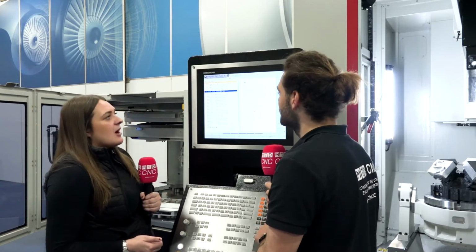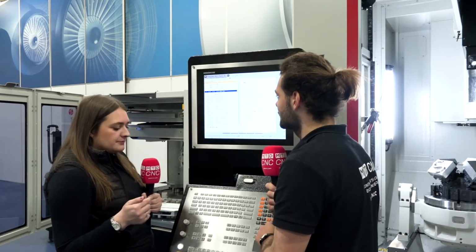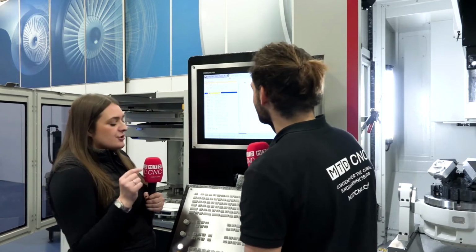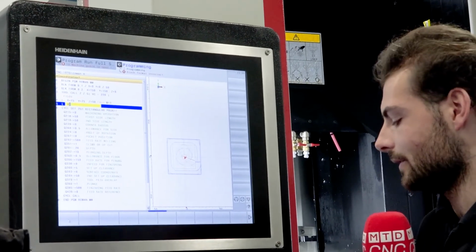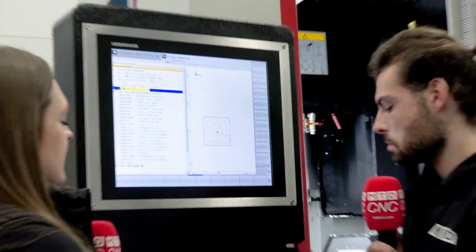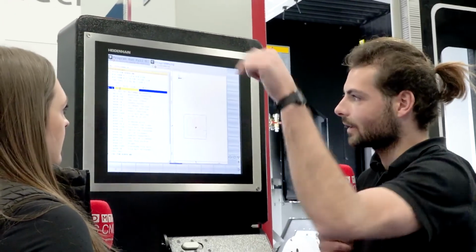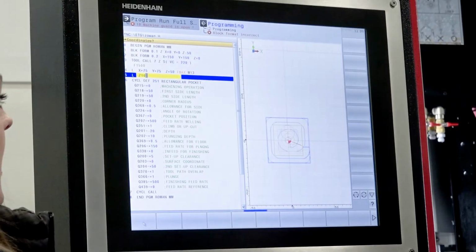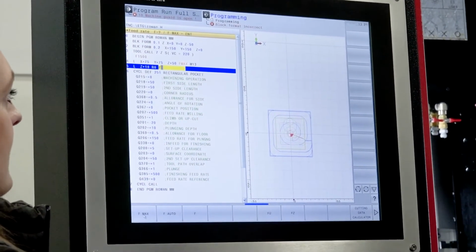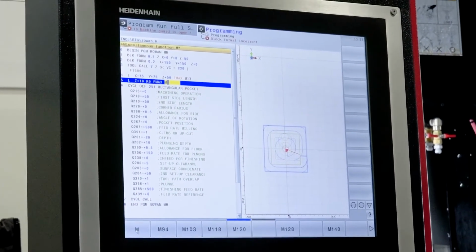At the end of that, I wanted to quickly do another line. Scroll across with your arrow and go to Z, and then just go to Z10. So we're going to come across to X75, Y75, and come down to Z10. Hit end, and put F max on that as well. Then we defined our cycle.